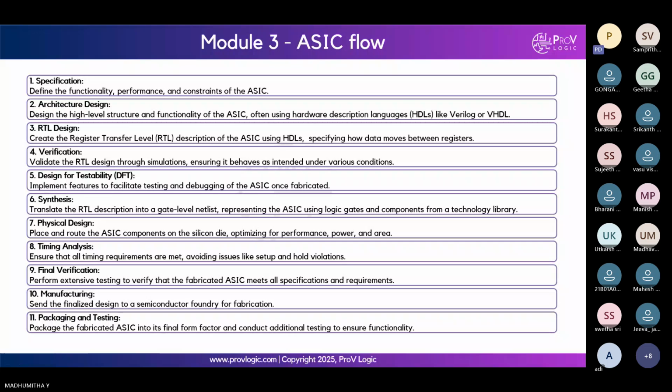So tape out means we have successfully pushed the GDS layout from the design team to the manufacturing team. That will happen after this tape out is done. The manufacturing team will take charge. They will start manufacturing the IC and the semiconductor foundry will take care of this.